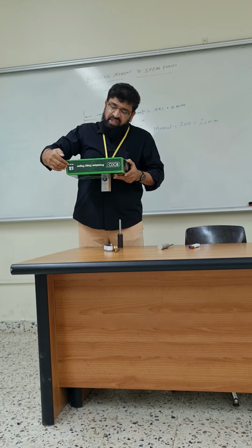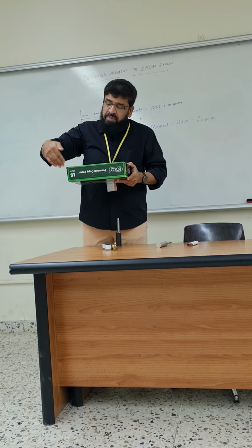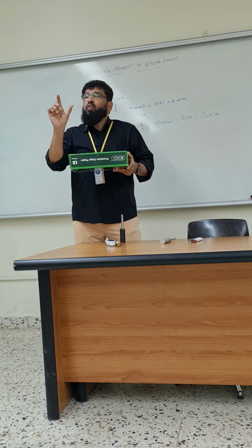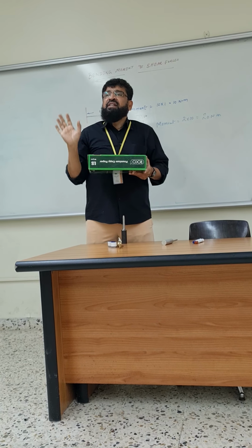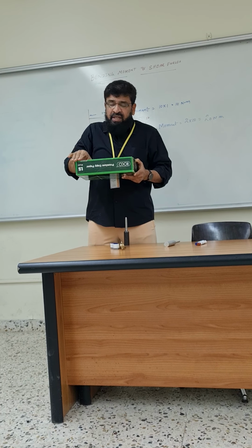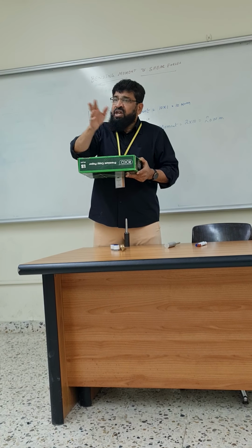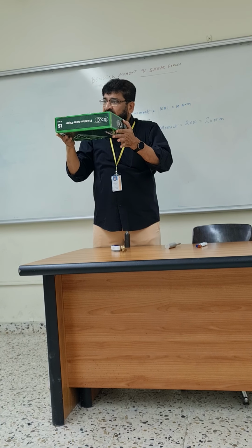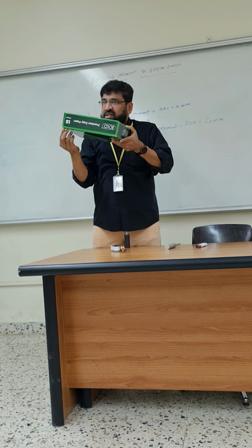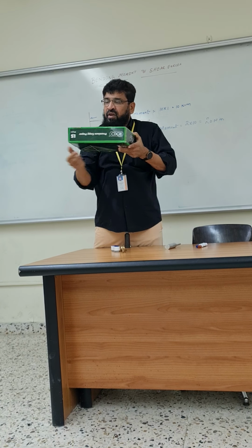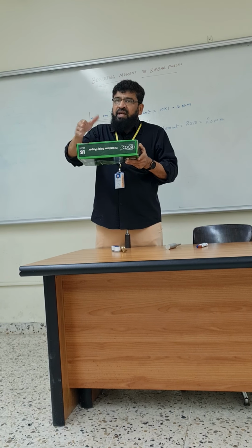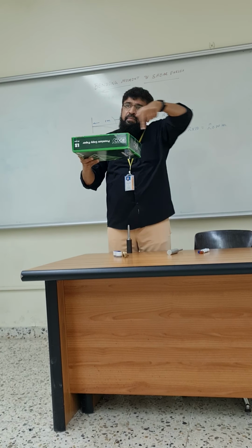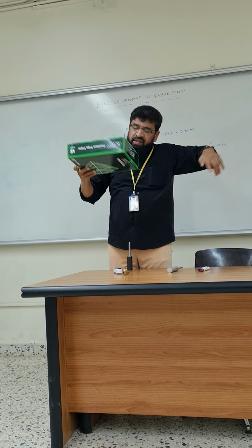Understand? Let us say this distance may be 20 centimeters. He can tell you 1 Newton per centimeter. Understand? 1 Newton per centimeter means how many centimeters do I have? 20 centimeters. 20 multiplied by 1 Newton, that is, 20 Newton is the weight of this. Is this clear? Because the distance is 20 centimeters, 1 Newton for each centimeter, multiplied by 20, so you have 20 Newton. From the midpoint I multiply it. Okay? This is the way I do it.